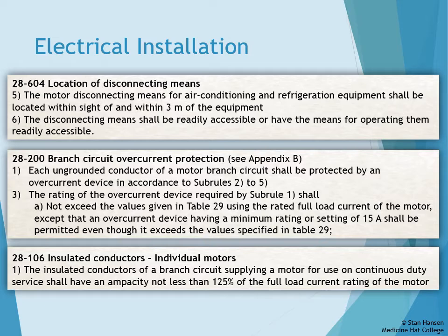For our low voltage wiring, it should be 18 gauge, but that is up to a maximum of 35 meters. If we go longer than 35 meters, we have to upsize our gauge for our control wiring to 16 gauge because of voltage drop that's associated with the distance.